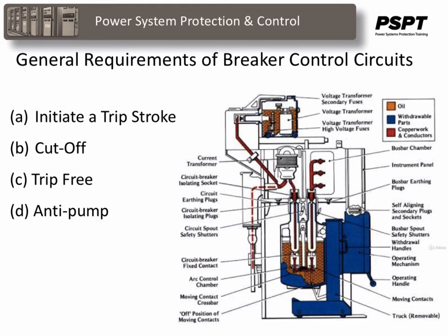Anti-pump. When a breaker is closed and a trip-free operation results, the close and trip stroke will be completed in a very short time. For a modern pneumatically operated high voltage breaker, the complete operation will take less than 1/2 of 1 second. Thus, it's quite likely that the operator will still have the control switch in the closed position. Means must therefore be provided to prevent the breaker from closing a second time, even though the operator is holding the control switch in the closed position.